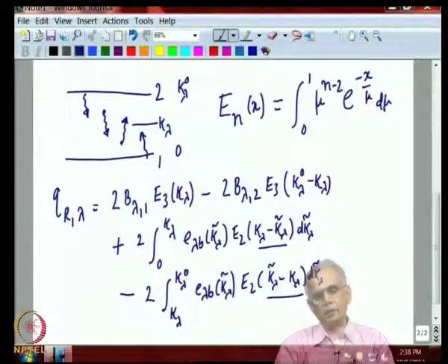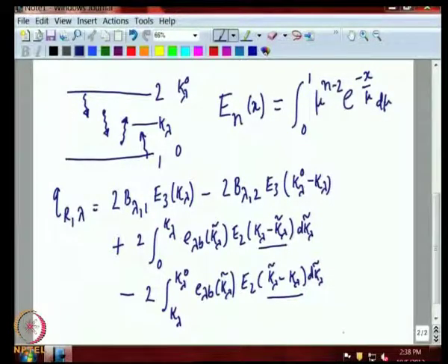On the other hand, in the case of radiation, the temperature in the middle of a gas in an enclosure may depend on what is happening at the wall, because some of the photons that are emitted at the wall can go right through the medium without being absorbed and directly interact with the region you are concerned with.